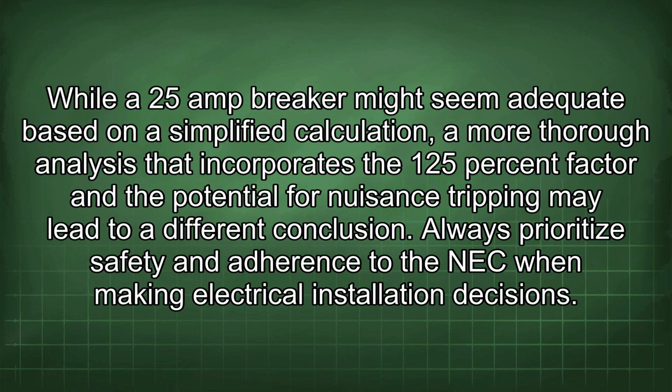While a 25 amp breaker might seem adequate based on a simplified calculation, a more thorough analysis that incorporates the 125% factor and the potential for nuisance tripping may lead to a different conclusion. Always prioritize safety and adherence to the NEC when making electrical installation decisions.